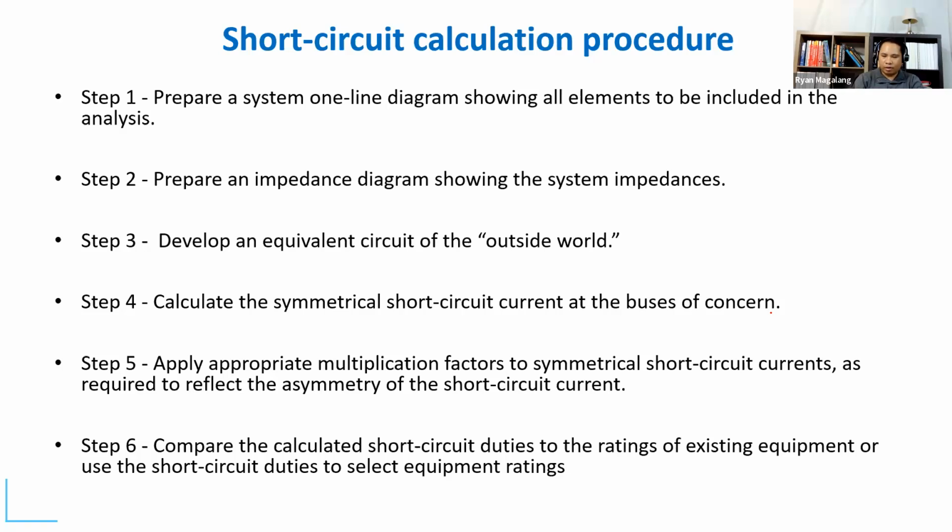So you're gonna get your panel board schedule, your load schedule, cable schedule, and things like that. And software such as, let's say, ETAP, SKM, what else? EC Power, they have built-in databases.